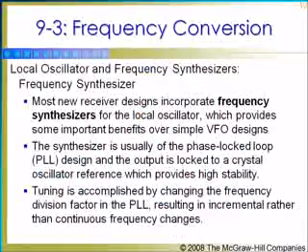The next one is the frequency synthesizer. Most new receiver designs incorporate frequency synthesizers for the local oscillator, which provides some important benefits over simple VFO designs. The synthesizer is usually of the phase-locked loop design, and the output is locked to a crystal oscillator reference, which provides high stability.